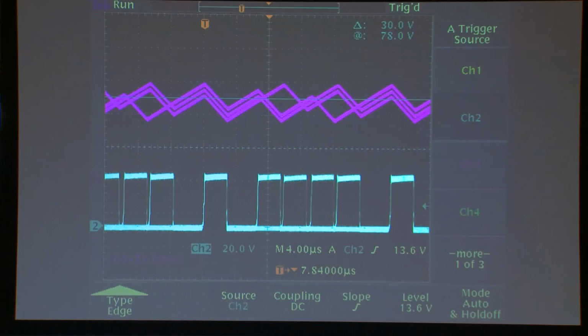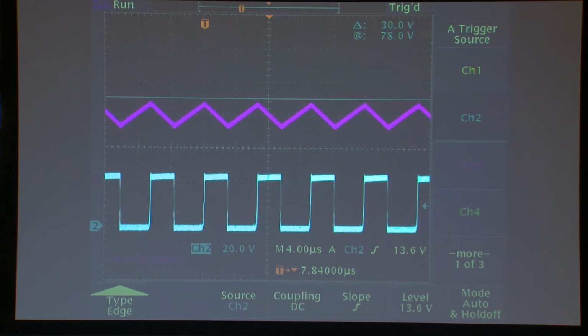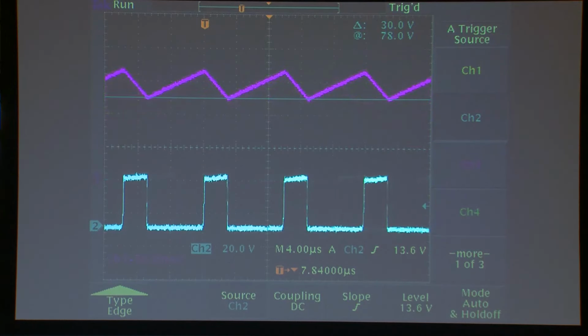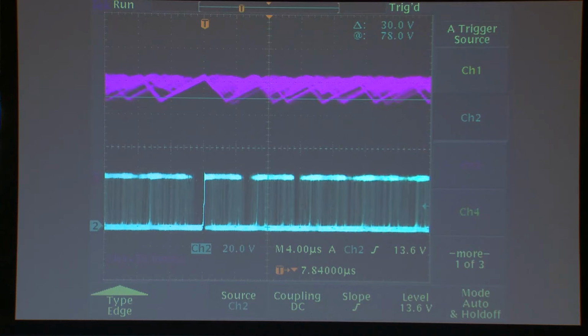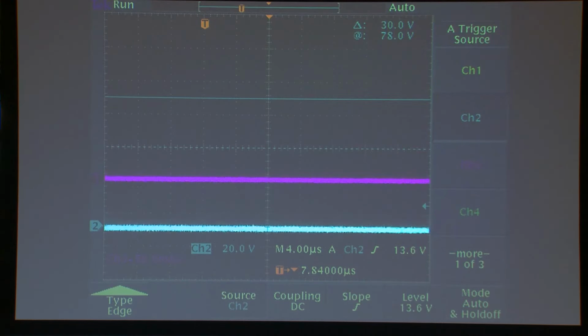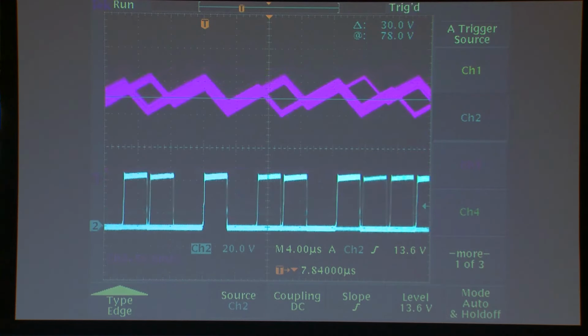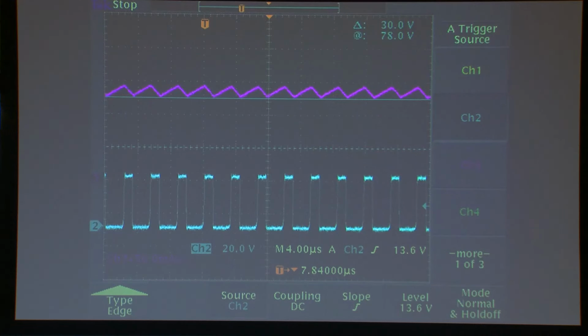And I should say that this is a function of the voltage. If I have a low boosting ratio, it goes away even without a compensating ramp. But the higher I go, because of that ripple instability, I get some really funky behavior. If I throw in my compensating ramp, there, I get nice steady state operation. Okay? So, that is current mode control for you.